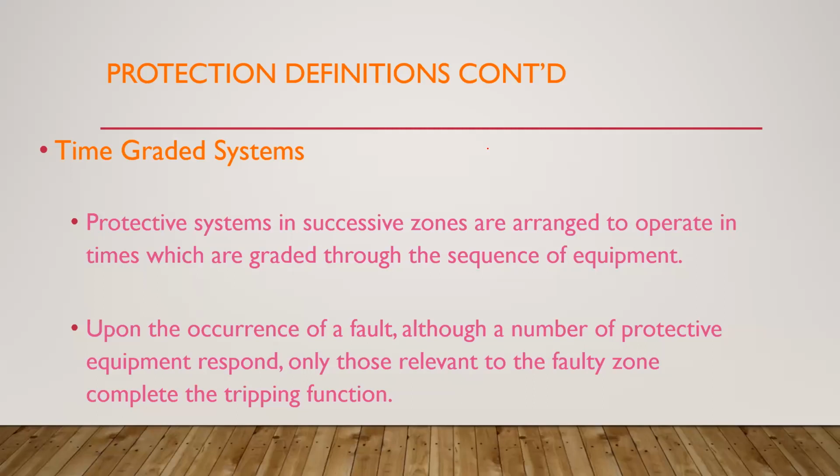So in protecting the system, you remove the generator because, remember I said before, your generator is one of the most pampered pieces of equipment in the power system. You can't afford to lose your generator, so you remove it from the system for its own protection.